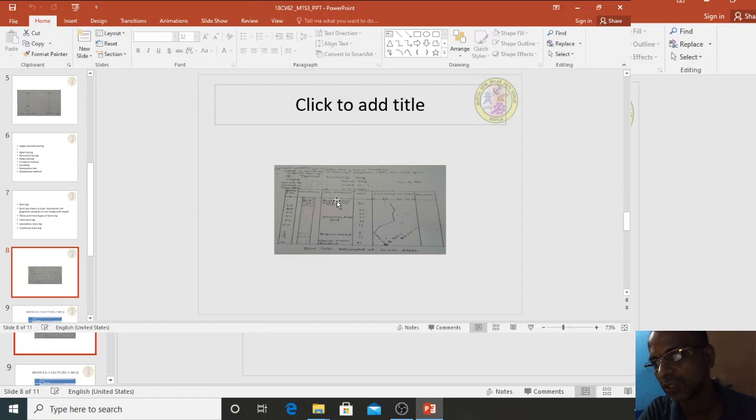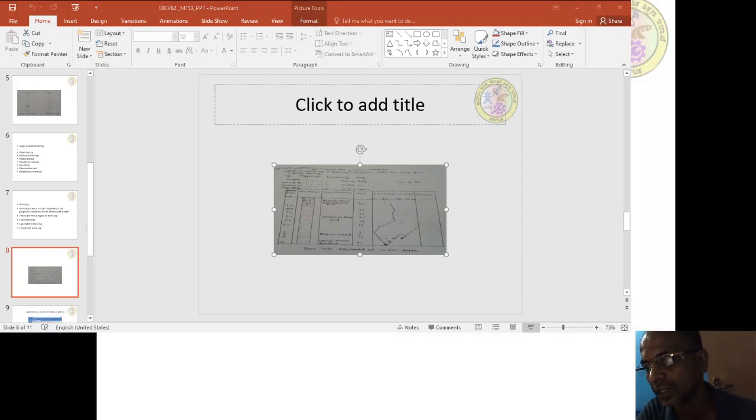See here, in this particular graph, the bore log is composed of the type of project and the name of the boring agency. You can see what project that particular bore log represents, the bore log hole number, the strata, and the depth at which refusal has taken place, that means up to which we stopped.